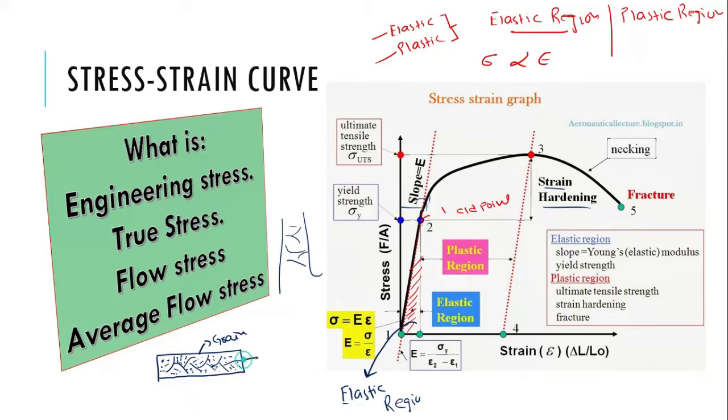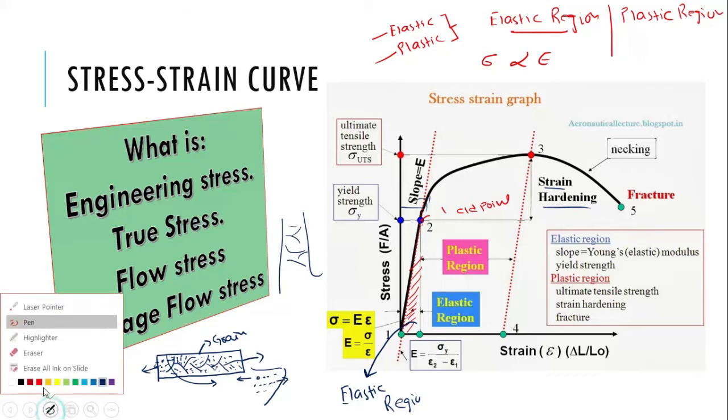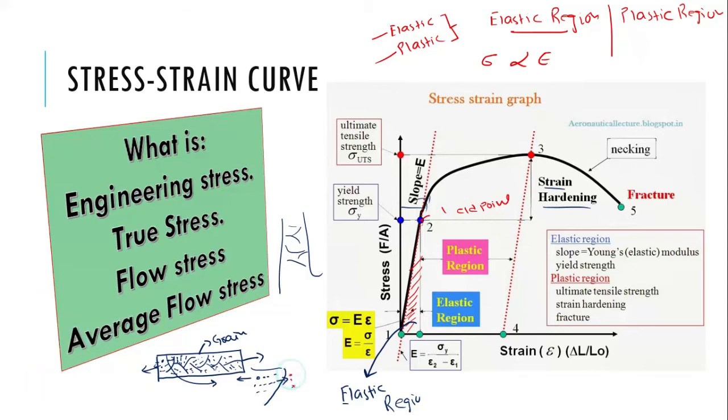So once such a material is under stress and you apply force, sliding occurs in the layers of atoms. If you see each grain, I am just enlarging this grain, the atoms arranged here will start to slide over each other, and this sliding will continue until these layers reach the grain boundary. Because on the other side of the grain boundary, the arrangement of atoms is different. Now atoms are arranged in some other pattern like this one. This is some other grain, let's suppose.